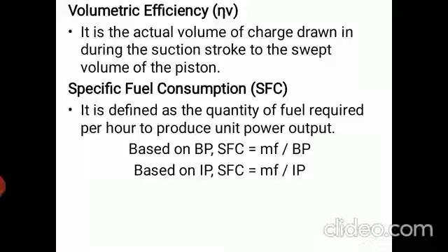Indicated specific fuel consumption means if you are finding fuel consumption with respect to indicated power, that is termed as indicated specific fuel consumption. BSFC means if you are finding specific fuel consumption with respect to brake power. Okay, then next, fuel consumption in layman's terms we will call economy. Economy means for a given period of time, how much fuel it is consuming to produce 1 kilowatt of power output. That's what we will mention as economy.